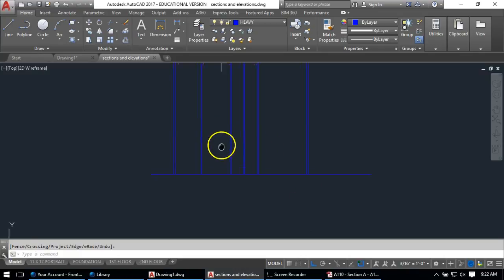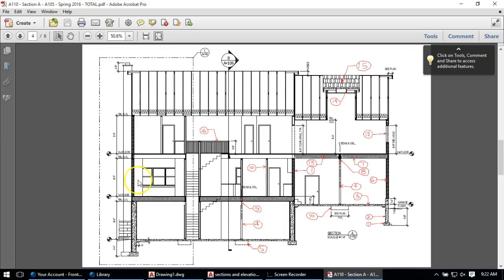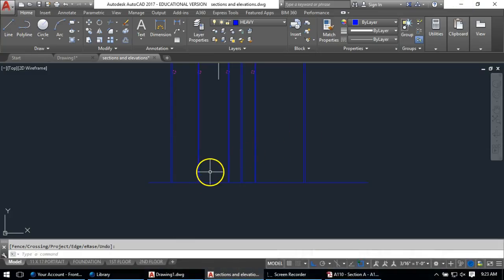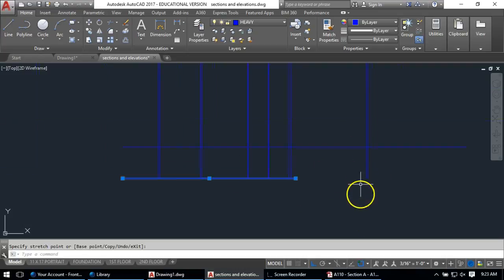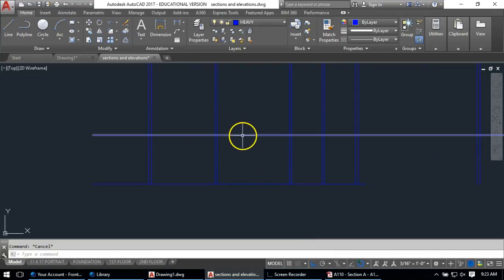And then what I'll do is I can set the ceiling height, which according to our drawing is 9 feet. That's what that says. That says it's 9 feet right there. So I can just offset 9 feet because that's my clear building height, right? The reality is, again, I'll have to come back because I forgot about the garage, right? This line's actually going to stop somewhere internal, and I'll clean that up, and this line will go a little lower, and we'll get that all worked out as we need to. But I'm basically setting up my floor height and my ceiling height, right?